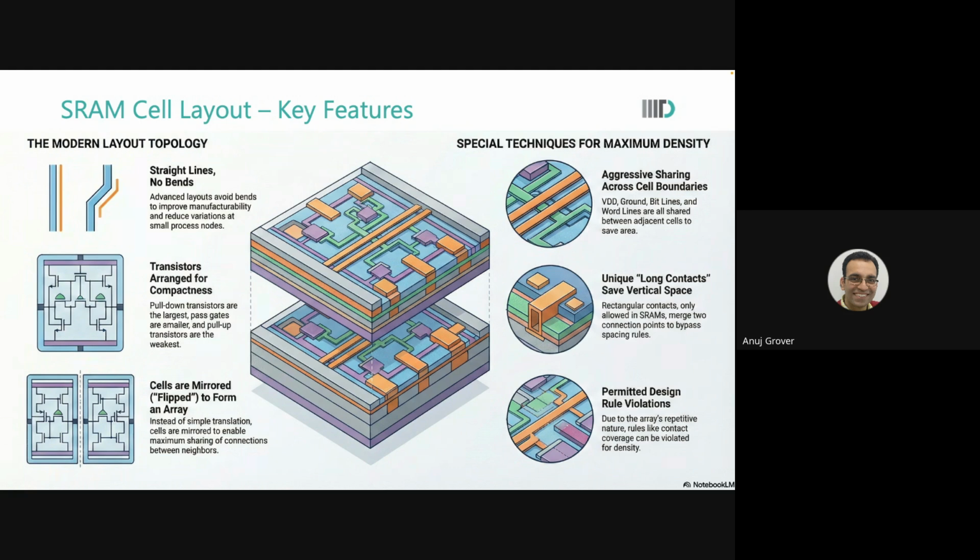You were not covering the full contact. It means there was some extra resistance that was going to be there. How much extra resistance do you allow? So you violate that distance also. Then you say, okay, reduce the contact coverage also. You don't put all the burden on only one DRC.